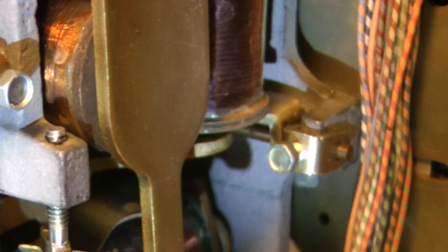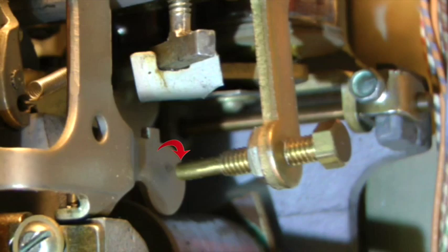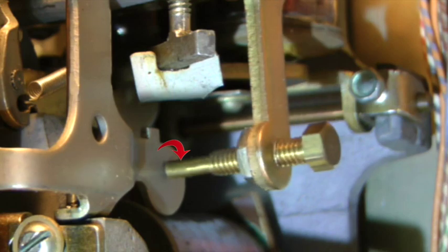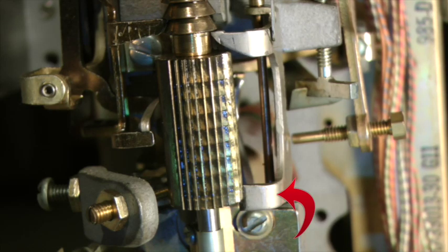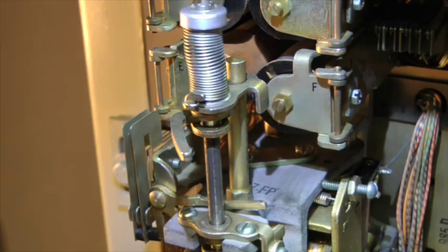The release of the F relay closes the energizing path for the release magnet, causing its armature to operate. The pin of the armature strikes the head of the double dog, causing the double dog to pivot and disengage from the teeth of the ratchets. The tension shaft spring now forces the shaft and all of its attached apparatus to rotate anti-clockwise to the rotary normal position.